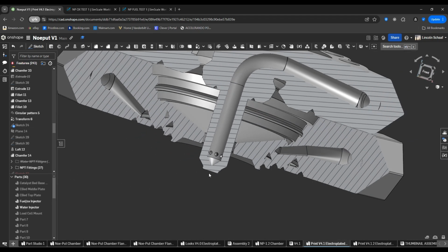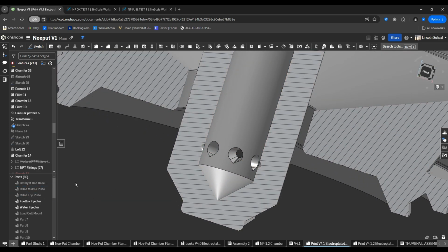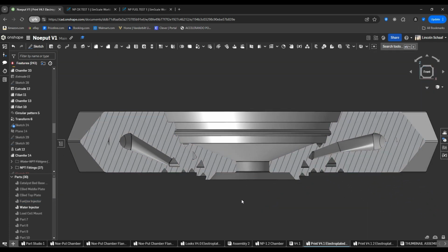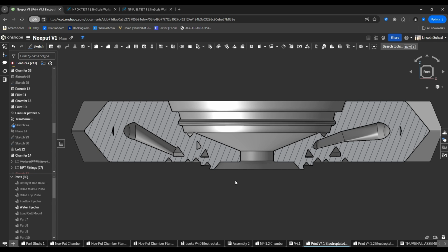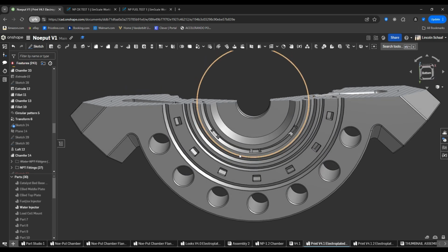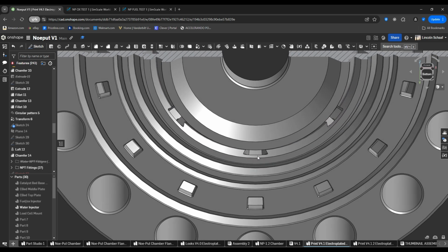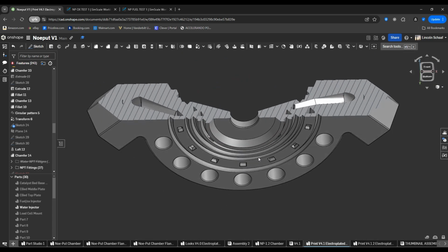This is because the most combustion will happen around these 7 holes in the pintle. Thus, the hot spots in the engine will also correspond with those holes. So we want the most cooling to be where those hot spots are, so that the combustion chamber remains intact. Therefore, most of the water cooling exits through these holes and then spreads out from there, with weaker cooling in the spaces in between the holes.